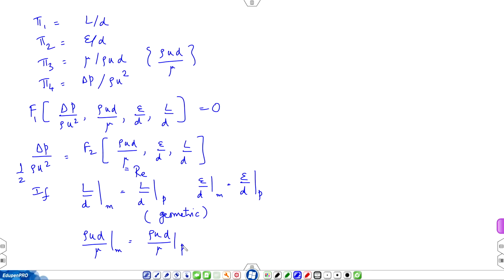So, what are the forces here in Reynolds number? We have not done it, but you may think of rho as being associated with mass and therefore inertia, and mu with viscosity and therefore viscous forces. So, it is a ratio of inertia to viscous. That is a tentative explanation.